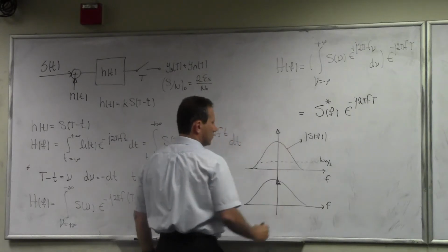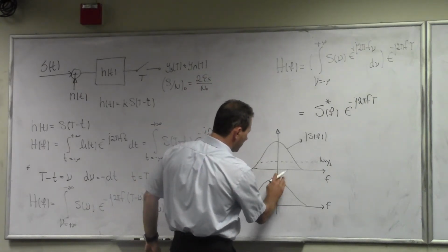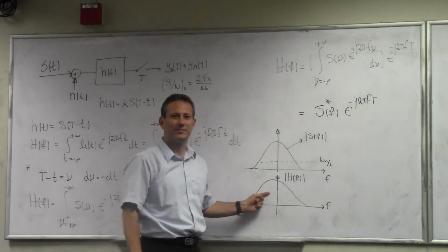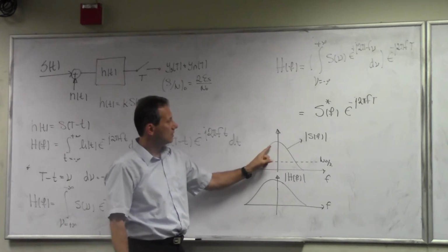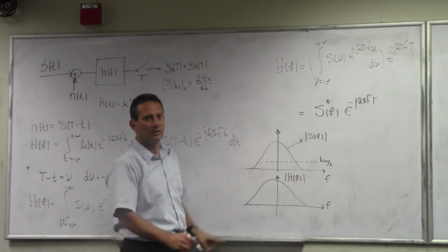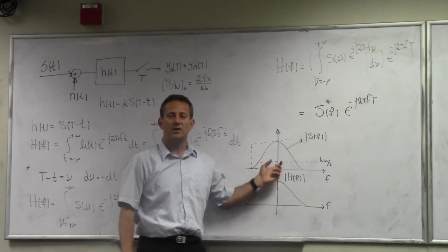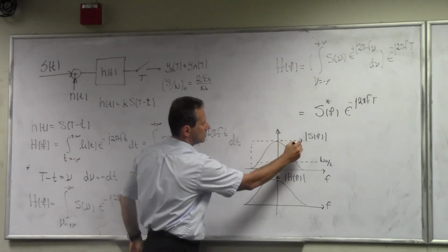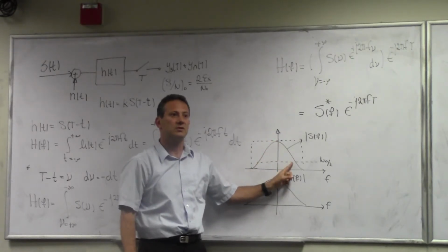So what's the big aha factor here? The big thing that should jump right away is that this is not an ideal filter, right? What does the ideal filter look like? Let's say I'm doing analog communication and I'm trying to receive this signal S of f. What would be my inclination to do in terms of filtering? To put a box like this, right? And I would say, let the signal go through and reject as much noise as possible. Remember communication theory: what is an ideal filter? It's flat across the top. It's flat in the magnitude response, and it has a linear phase. It's flat in the magnitude response so that it does not distort the signal itself.